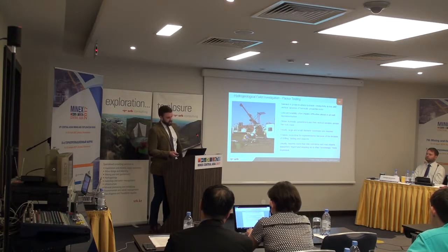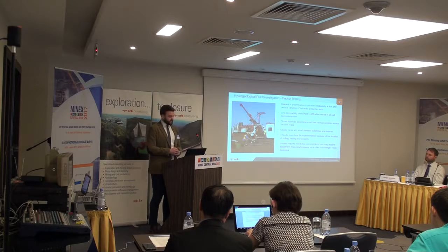Low permeability often implies difficult problems in pit wall depressurization. Packer testing will give you an understanding of the hydraulic parameters and the vertical variation across the rock mass. As I said, they usually use larger diameter boreholes, supplemented with smaller holes that need to pair up for the hydrogeological monitoring.